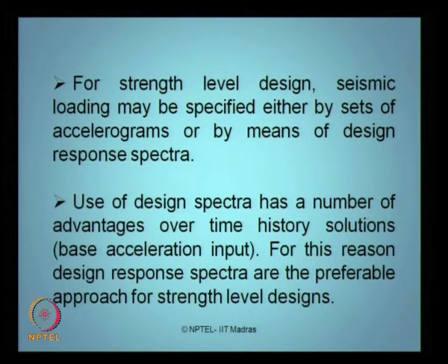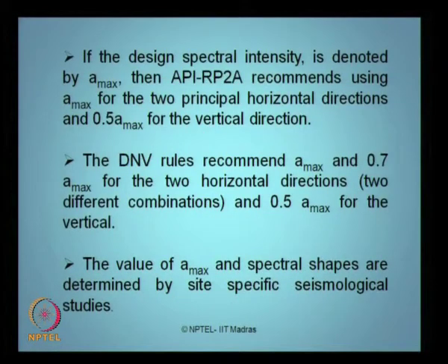For the strength level design, seismic loading may be specified either by sets of accelerograms or by means of design response spectra. The use of design response spectra has a number of advantages over the time history solutions, which are based on the base acceleration input. For this reason, the design spectra are generally preferred for strength level designs in offshore structural designs.